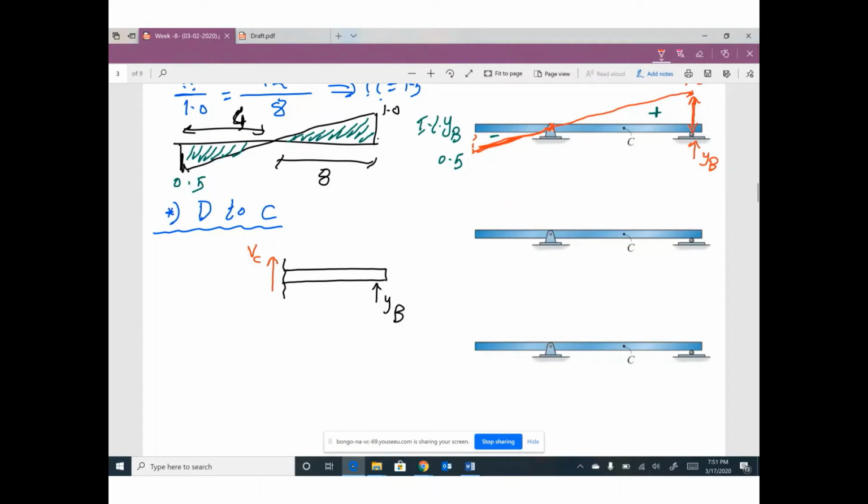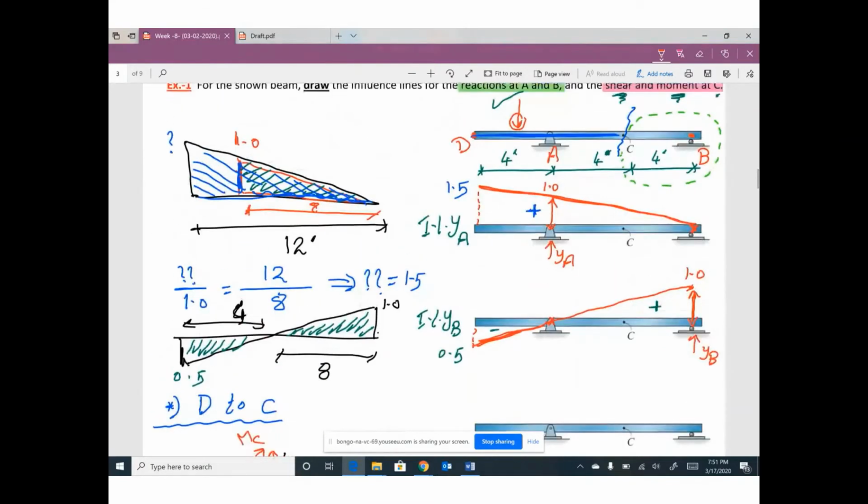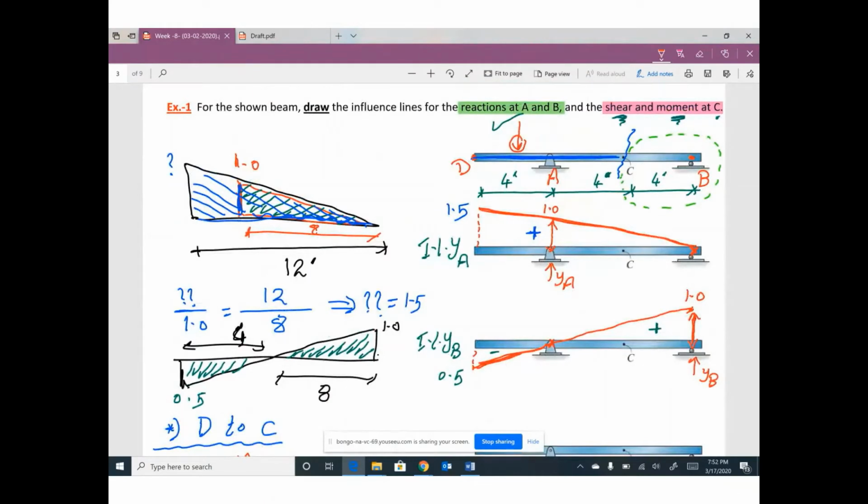We have shear and we have moment. This moment at point C would like to make this member smile. And remember this distance equals 4. One more time, the first trip of your moving load will start from the beginning of the bridge until point C. Your moving load is playing on this part of the bridge.